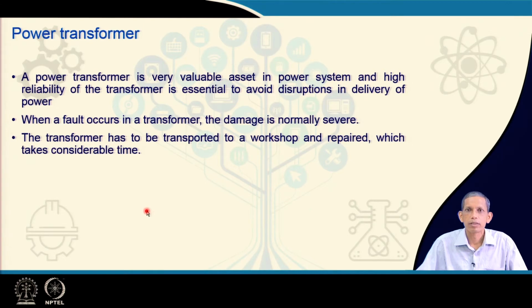Further, not only is there disruption in power, it is not momentary; it is for a long duration until the transformer is replaced, unless there is parallel operation of transformers. A transformer is costly, so any damage is of high economic value. Further, replacement of a transformer takes a lot of time because of transportation and long maintenance time.